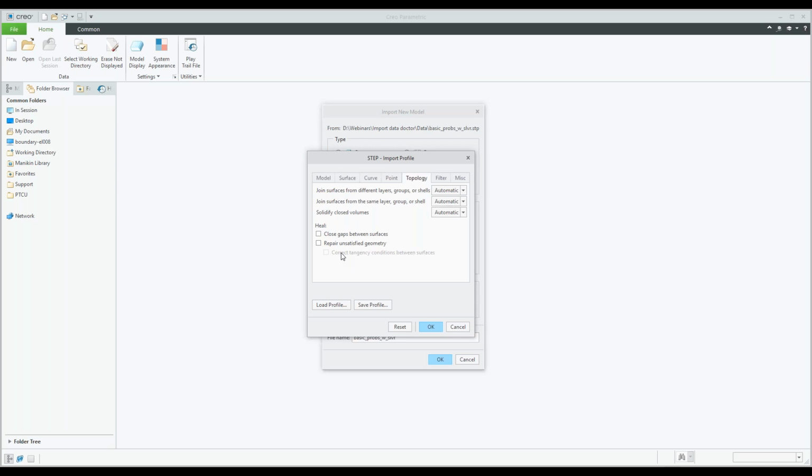So my tip would be keep this off for the first time you open up a component. See actually what it is, how many errors there are. Is there a lot of missing surfaces, open edges, things like that. And then when you do your second run, maybe say you'll close some gaps and things, and just check how long that will take. And if the result is a lot better, then you know you can go with those settings. So play around with them, test them a few times before you get cracking and start fixing up that geometry.